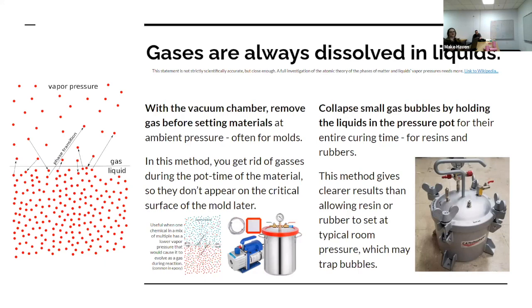Yes. And in mold making and casting, your number one enemy is bubbles. Always bubbles. There's just entrapped air. Yeah, you're always trying to get them out of there. And pressure is a great way to do tiny things with little details that you really need to force the material in to get all the detail.